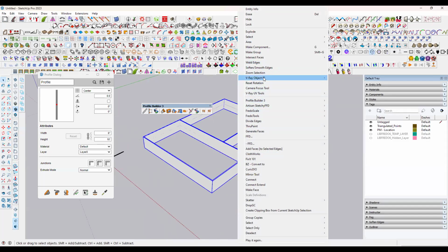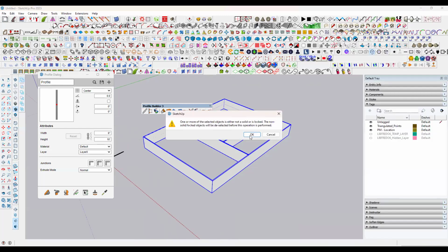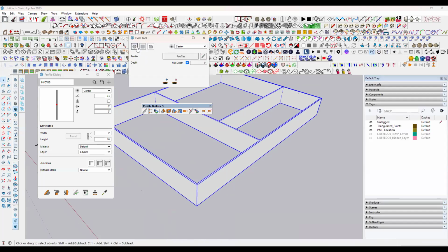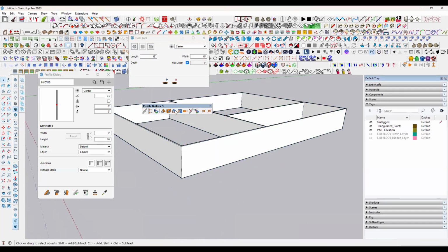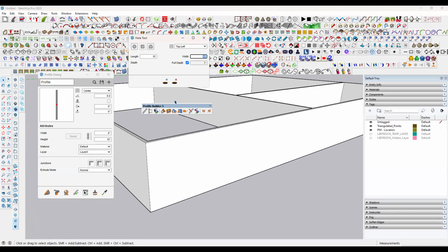We will have it in the solid tools. Yeah, here maybe. So I can make it a union, or maybe keep it like this, no problem. Then if you want to make holes directly on the walls, I'm selecting this one. If I click on the space, I can select here, maybe the center, whichever one you want, click this one and type the dimensions.